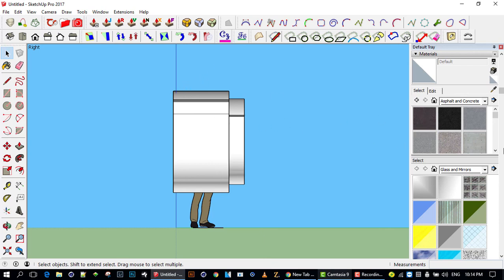You're able to create duplicates by dragging the first one out and then going the multiply sign, the asterisk, and the number of duplicates you want to make. Or if you want to press the plus sign, drag out one to a spot and type divided by a certain number, and it will create copies in between each other. And then to get back to the normal select tool is the space bar.